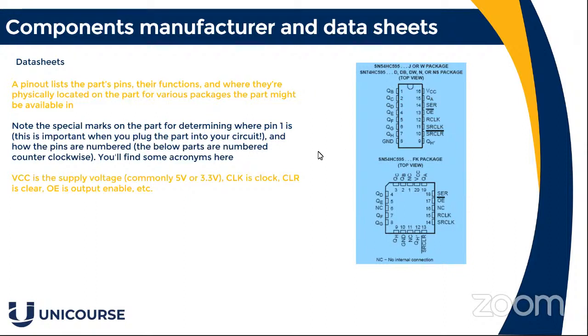So it's important that you know what voltage you're working with, because sometimes the voltage that you need to power up that component may not be suitable for what you're doing. For example, if you want a portable piece of kit and it needs to be compact, and the actual device, the component, is maybe 12 or 24 volts, and then the suitable battery you can get is quite bulky, then it may not be suitable. So you may have to look for another component that's running between, say, 6 and 12 volts, so you can get the suitable power supply.